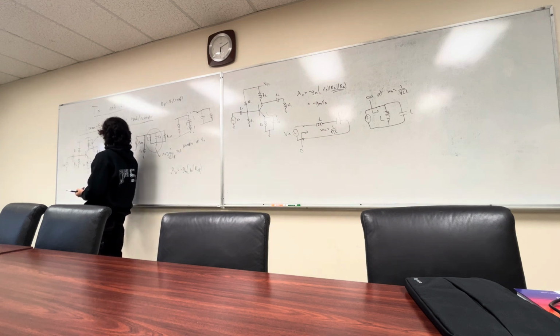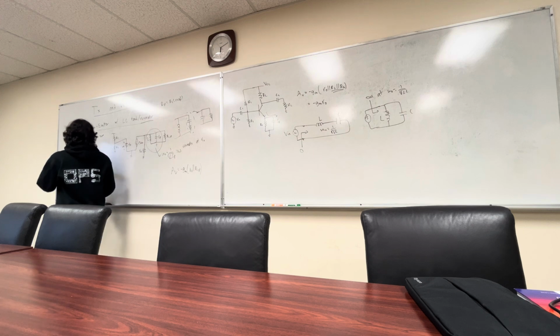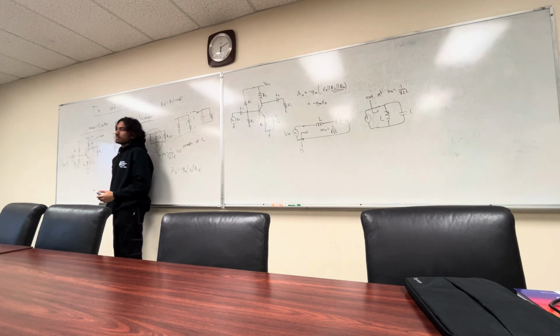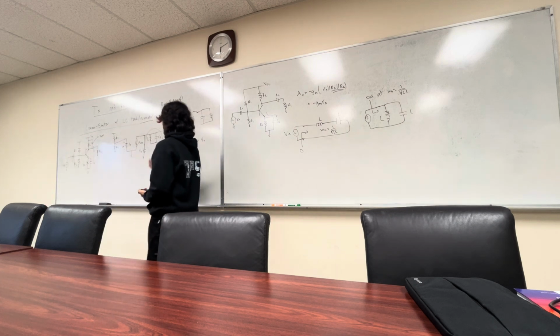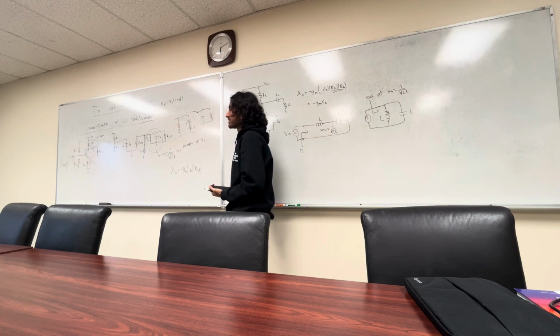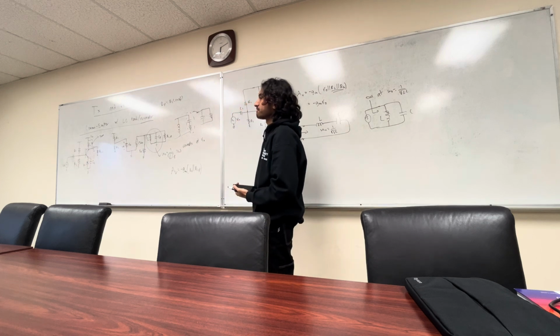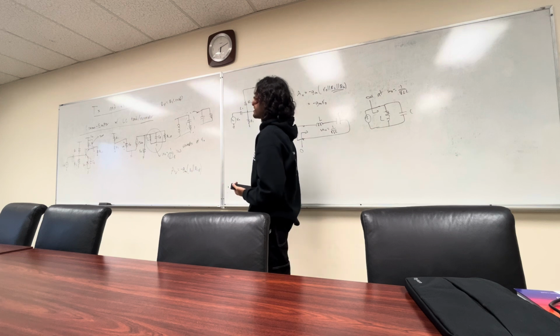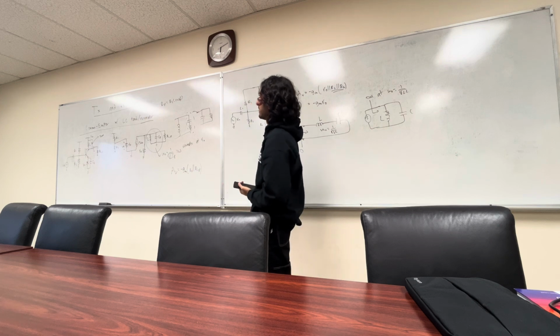This means that this is VCC, our collector is at VCC. Which means as far as making sure our collector is high enough above the emitter, that's guaranteed because it's at our supply.